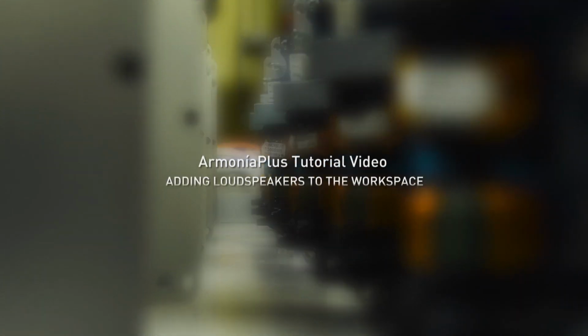In ArmoníaPlus, loudspeakers play a crucial role in the design of a project, as they will contain all the preset information that is necessary for a correct amplifier operation. To add a loudspeaker to the workspace, we go under Design, Add, and then we click on the speaker tool